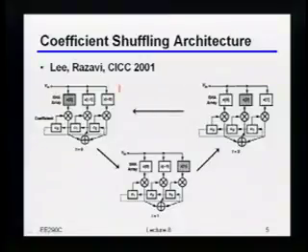Let's say I wanted to build this particular filter where, as an example, C0 is the main tap, C1 is the first post cursor, and C2 is the second post cursor, right? So the basic idea would be that I could sample these inputs in these three samplers here, then in the first phase feed them to these three multipliers, okay? So on that first clock phase, I've gotten that filter that I wanted, right?